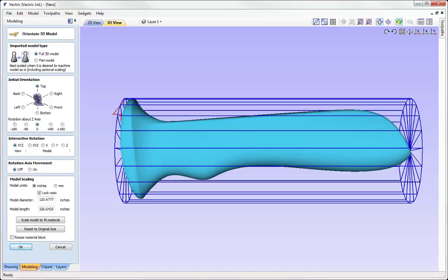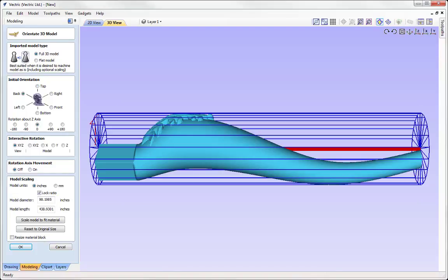For example, we're going to take a look at a cabriole leg. So we can see the rotation axis runs through our model, and then as our model curves down and back up again, the actual rotation axis is visible. Okay, so if we was to machine this as is, here we would see some very strange areas, as this area would be filled in because it's essentially an undercut. So the idea here is we want to look at really obscuring our rotation axis so that we don't have any undercuts and we can cut the model as best as we can as it is.